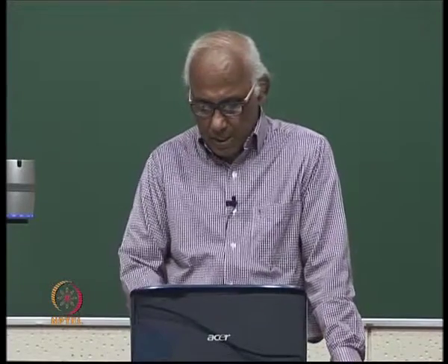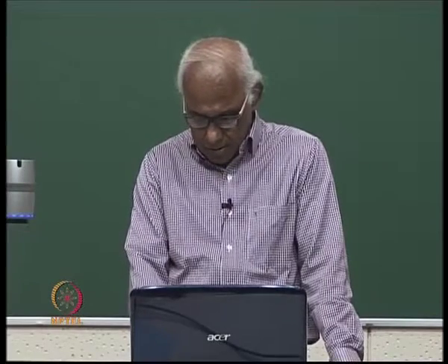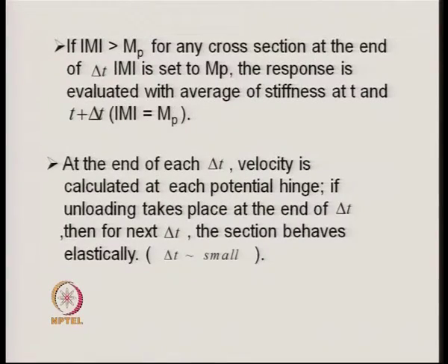When we get that incremental displacement, we add the incremental moment to the previous moment and see whether other cross sections are yielding or not.